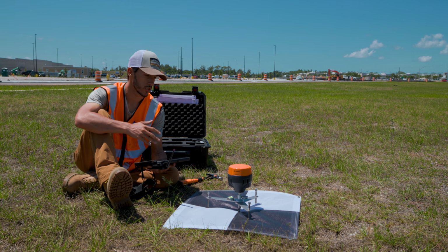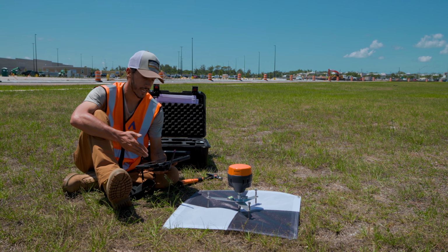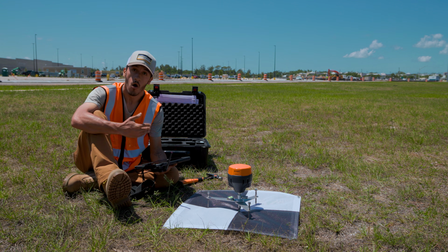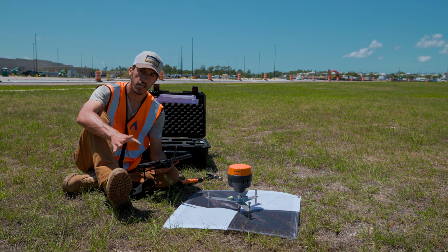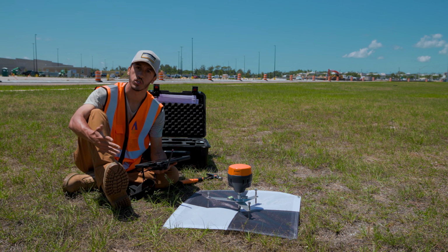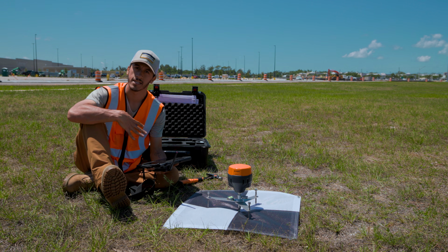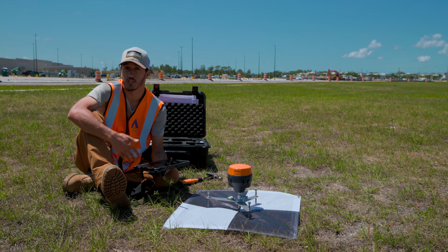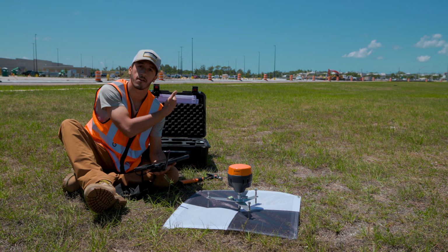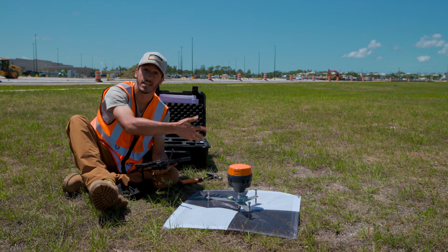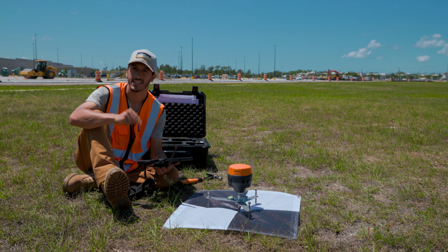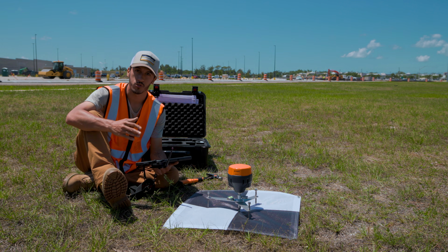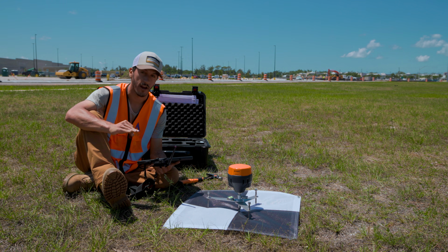So this is going to take measures for the next 30 seconds and average out this point. Once this is done, I'm just gonna do this 4 more times on this site. It does recommend at least a minimum of 2 checkpoints on site, but my typical workflow, I always do 5, which is perfect because you actually get at least 5 of these targets in your kit. So once this is done, I'm gonna quickly go and set these other 4, and then we'll be able to go ahead and get the drone up and running very shortly here.